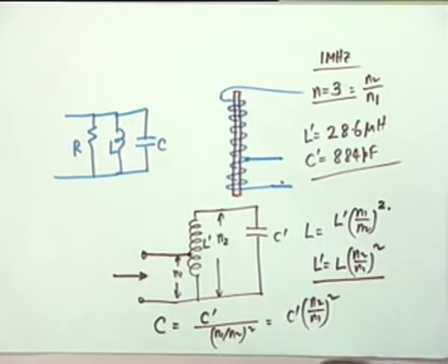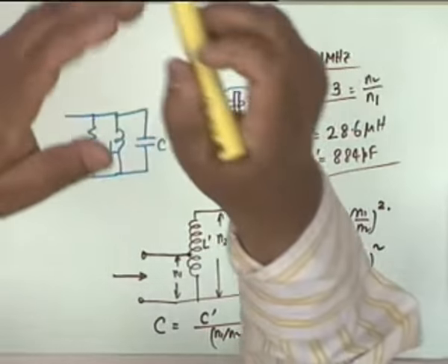Can you tell me any other reason why this auto transformer facility would be useful? Any other reason? Suppose the capacitance, you see, while inductance you can fine tune by putting an extra turn or half a turn or a quarter turn. Capacitance, there is nothing that you can do. It's only standard values which are available. What you can do is you take a standard value, then use a variable capacitor. Varactor is a diode. Okay. A variable capacitor is called a trimmer.